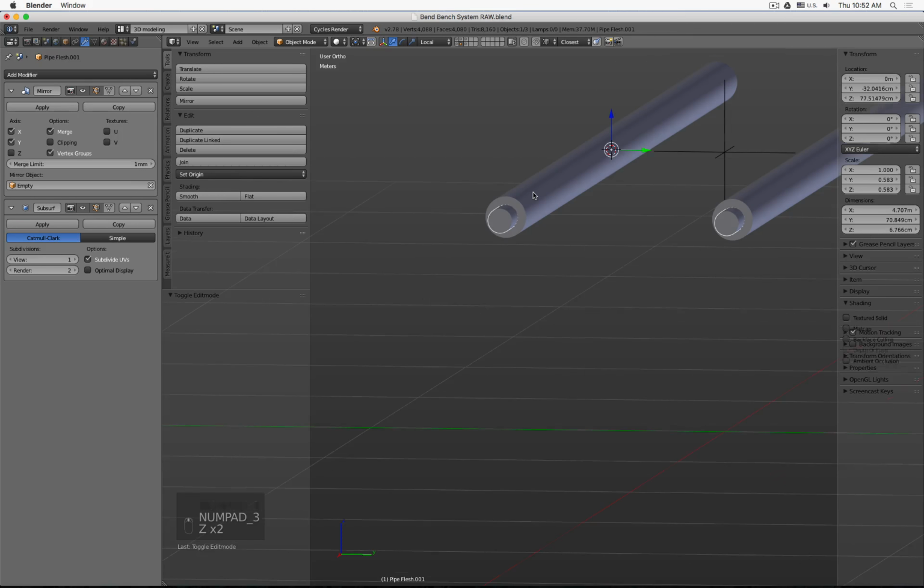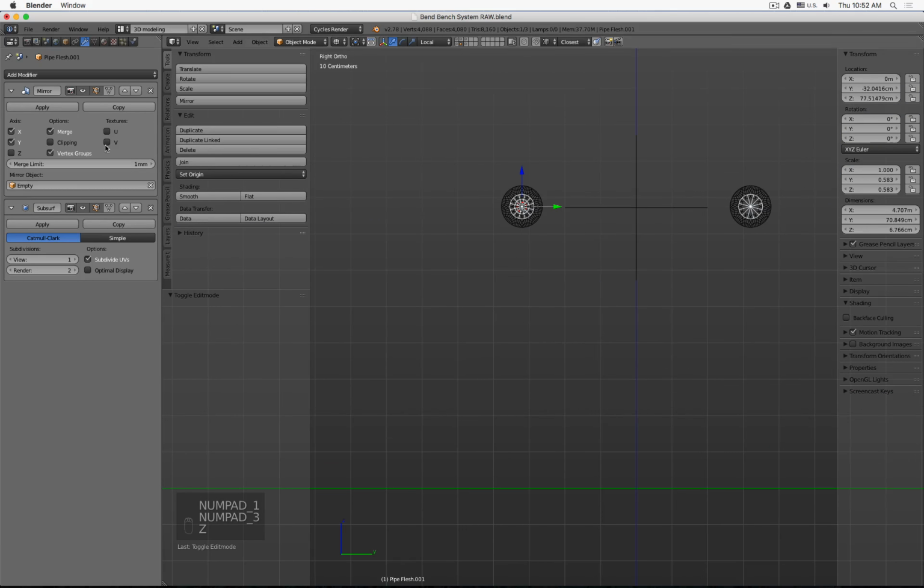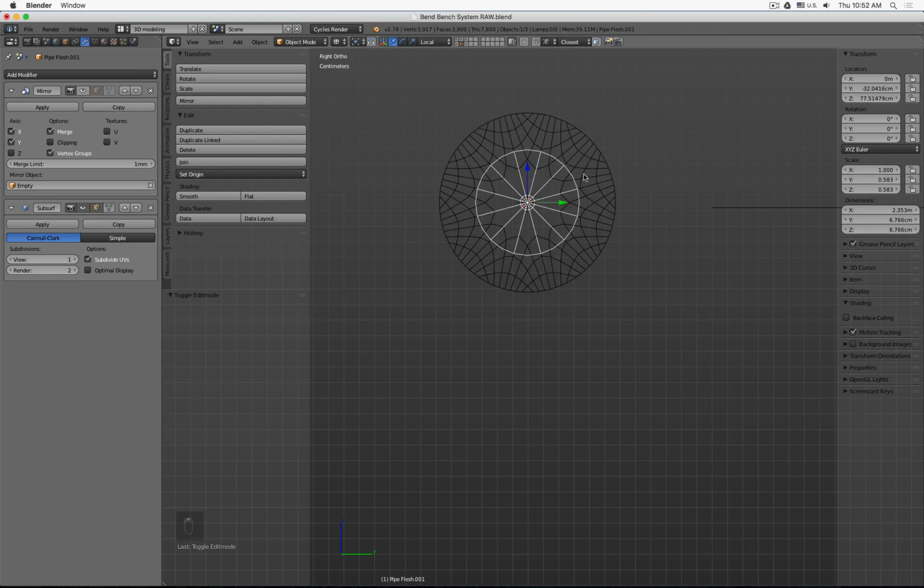Now we have the dimensions. Also, before we continue, let me turn off this one for a second, because I want you to see when we turn on the subdivision, the numbers change. So let's say we really want to have 7 centimeters, then actually we should scale this one in object mode when having the subdivision turned on.